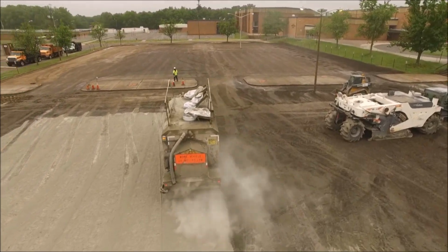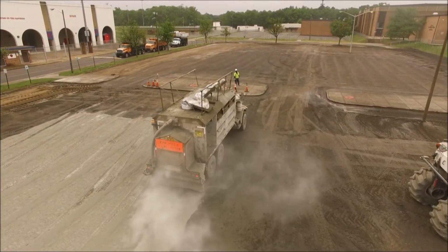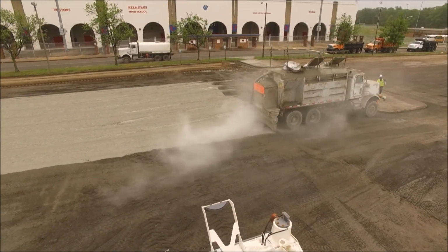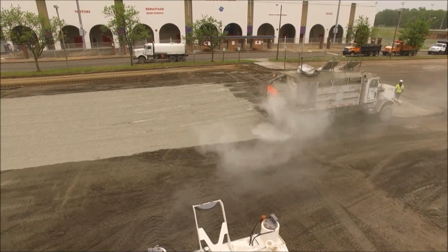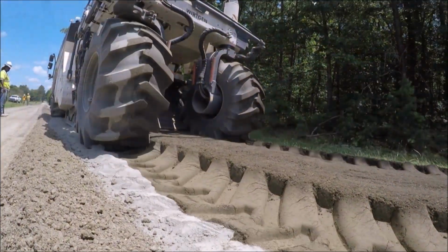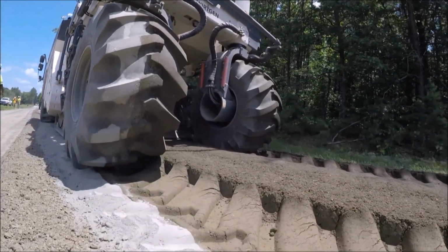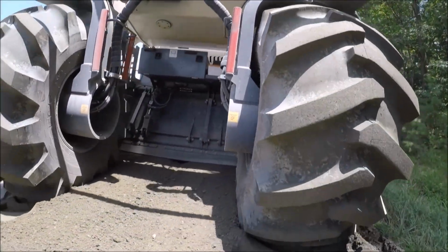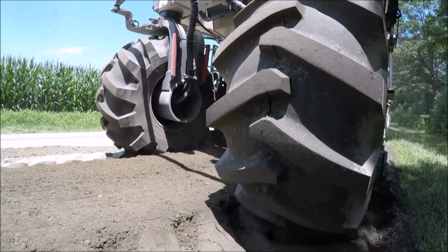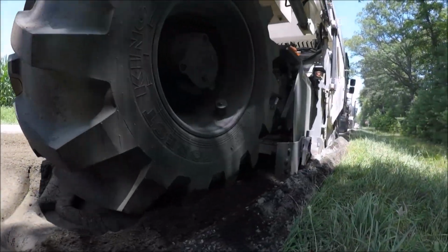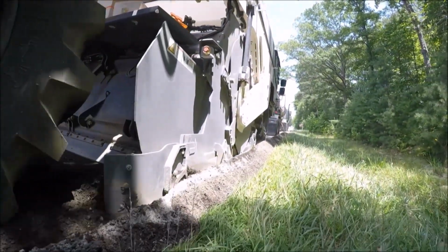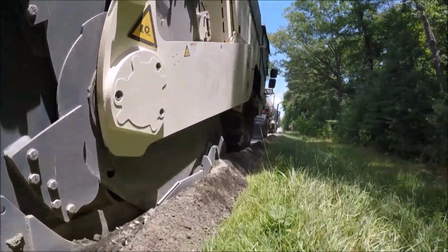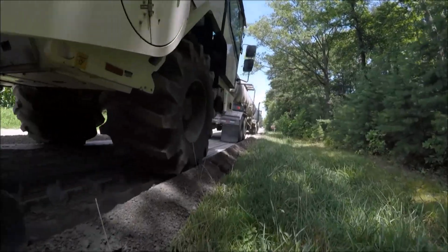Here they make several passes. Then the reclaimer will come back through and introduce the water and make its final pass to blend all of the cement with that lower grade material. So you're blending all that material together at 8, 10, 12 inches, whatever the design is. Historically, being able to monitor that water has been a challenge. With the technology we have today, we're able to monitor the water, the cement, and all of it in one pass.